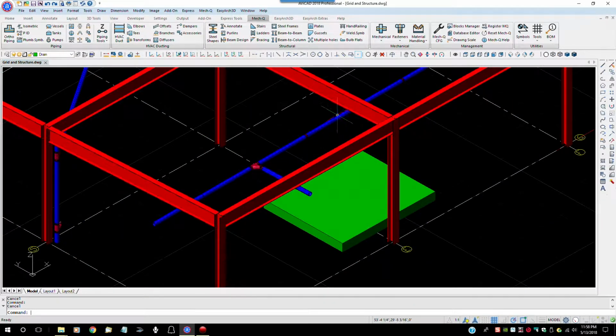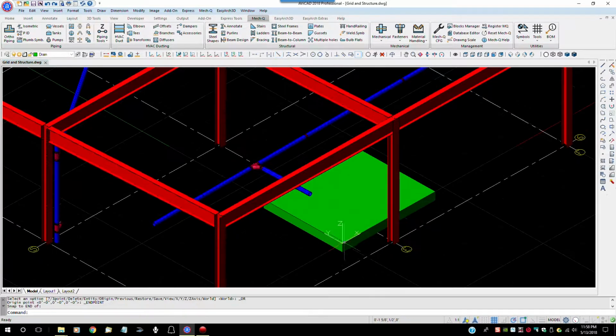This is the line we're looking at that has the node on the bottom of the pipe, which I gave you the distance off of the floor or the grid. But sometimes if you're in a spot where you can't get to the floor and you don't really know what this curb height or this pad height is, you can't always tell. So what we're going to do here is move this origin point here to the pad itself. Now when I check the ID right here, I'm going to get it off the pad height. And you can see that's 16 foot 3.